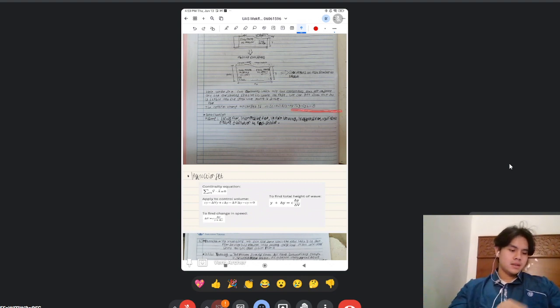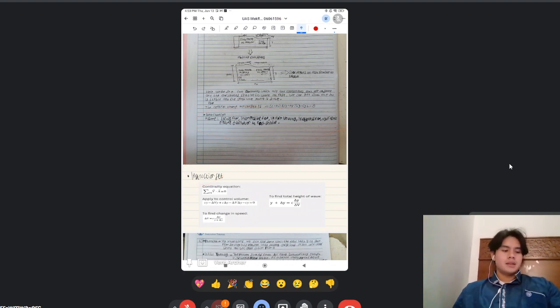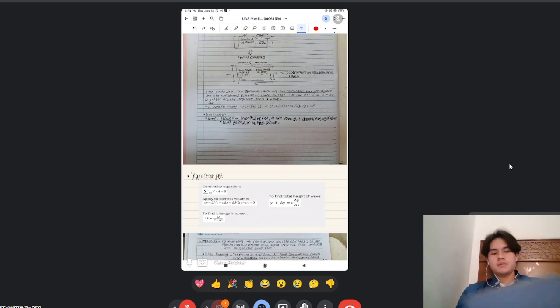But now that I can actually correct it and move on to the idealization and instruction set, I can tell you that for the idealization, we should assume that the flow is steady. It's an incompressible flow. There's uniform velocity. There's frictionless flow, hydrostatic pressure distribution at each section.